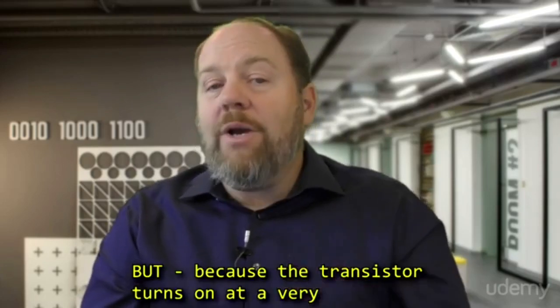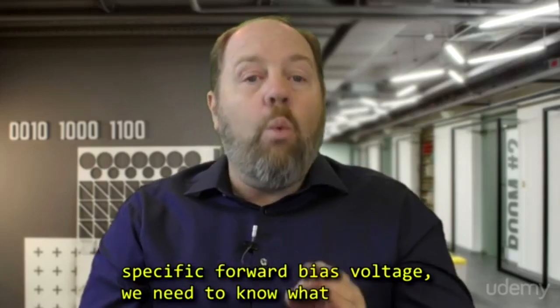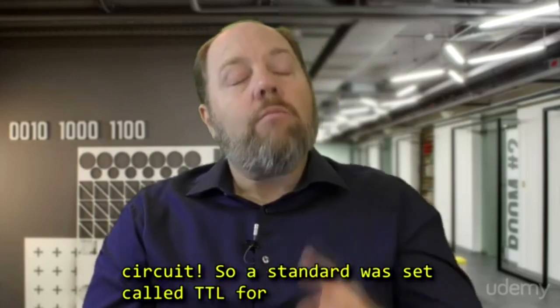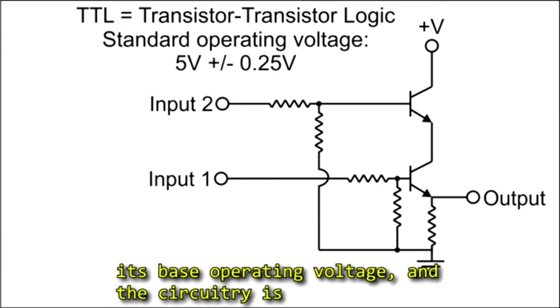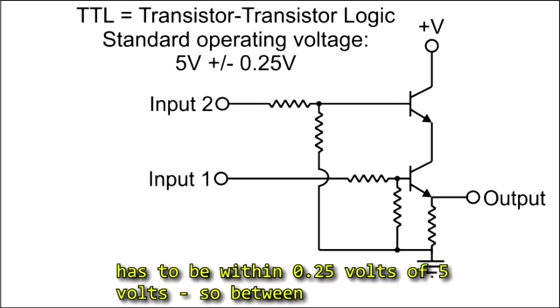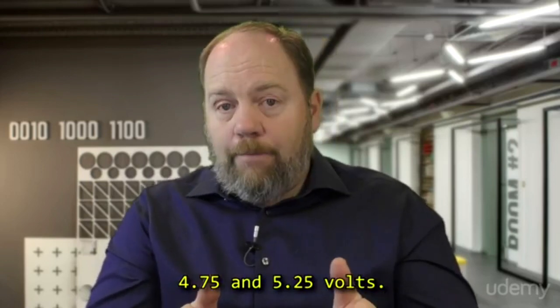But because the transistor turns on at a very specific forward bias voltage, we need to know what our operating voltage is before we even design the circuit. So a standard was set called TTL for transistor-transistor logic. TTL uses 5 volts as its base operating voltage, and the circuitry is designed around that standard. The supply voltage has to be within 0.25 volts of 5 volts, so between 4.75 and 5.25 volts.